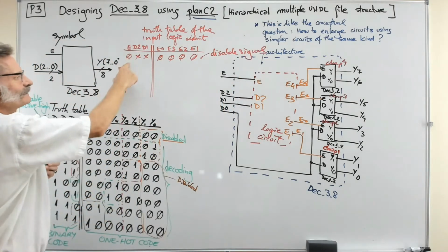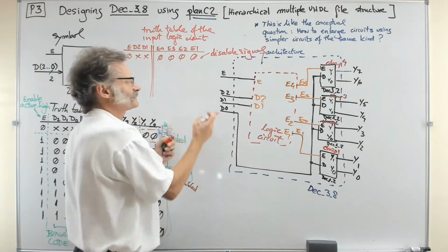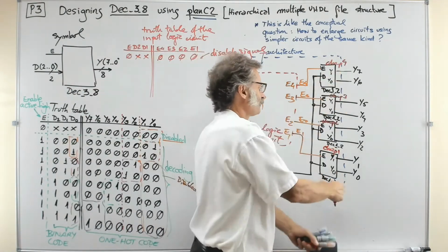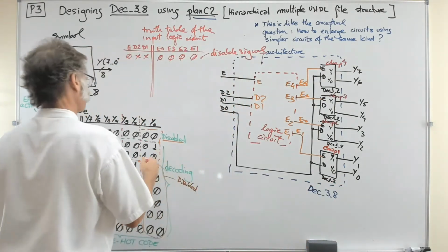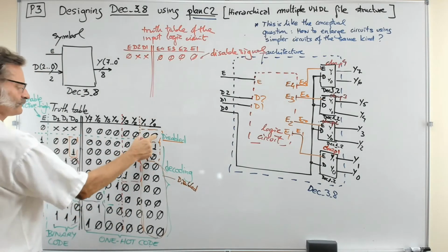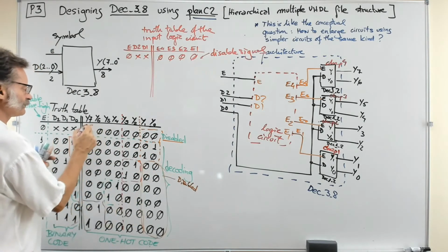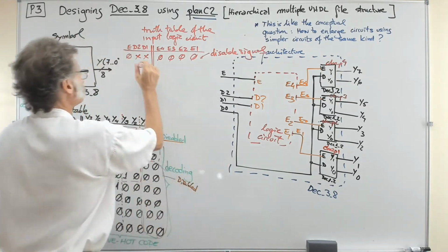If the input of this circuit is 0, the outputs must be 0, so that the 4 of them are blocked. And so, if they are blocked, you have 0, 0 by default. If E is 0, you have 0, 0 everywhere. So this is exactly what you like here. 0, 0 everywhere. So that is perfect. And then what?